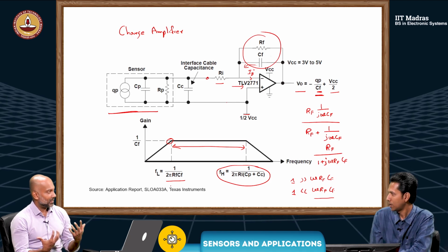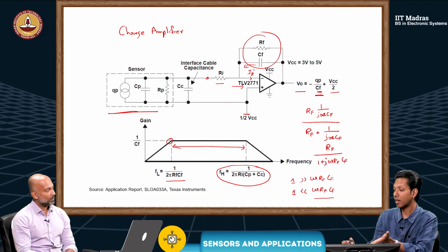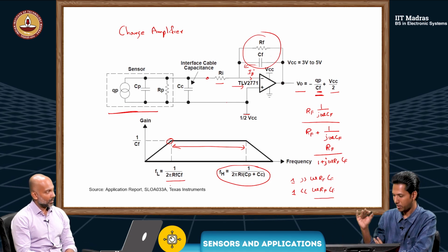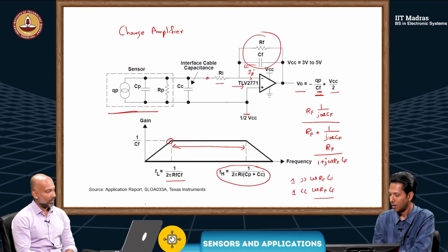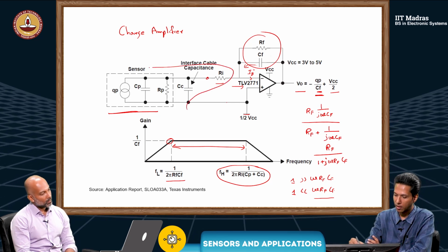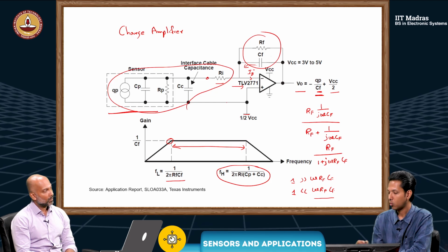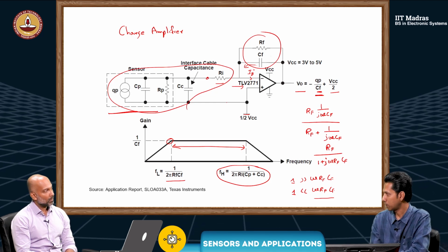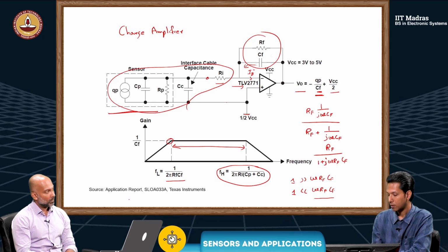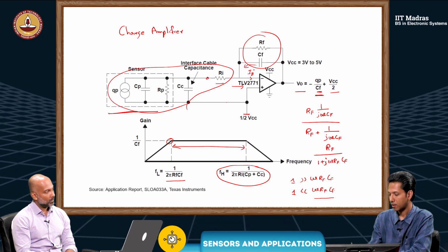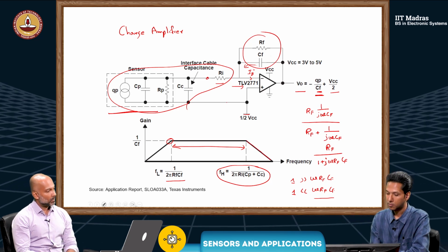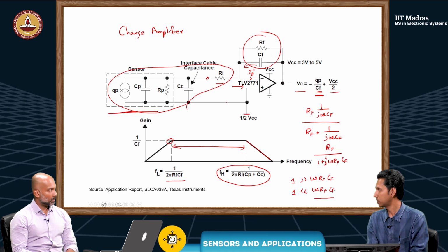It kind of absorbs that, so it can no more be an impulse; it will be a smoothened impulse. Students can look at what characteristic this Ri will give. It will introduce another pole here, and from there the output will reduce. So it is a nice example of a charge amplifier.